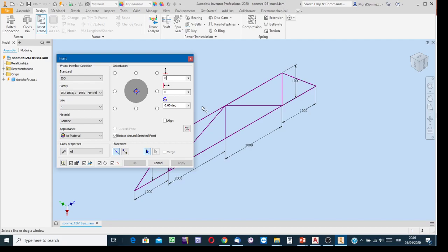Okay. The other thing here, placement option, saying that it is the skeleton of the member. Shall you indicate the member with 1 click or 2 clicks? Well, this is advantageous. Instead of, if you select this one, then you need to indicate terminal points, both of the terminal points. But here I'm going to indicate the member except terminals at any other point. It is easier. Okay. I'm going to talk about this angle facility later.